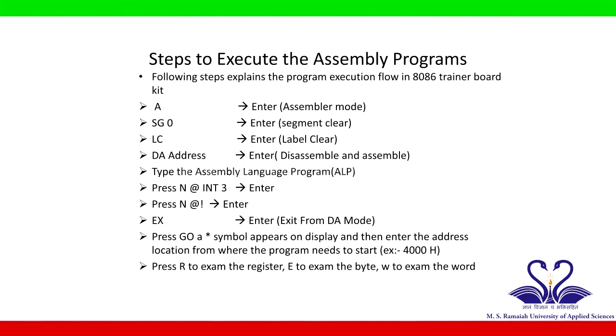Steps to execute the assembly programs. Following steps explains the program execution flow in 8086 trainer board kit. Type A. Enter. Assembler mode. Type SG0. Enter. Segment clear. Type LC. Enter. Label clear. Type DA. Enter.